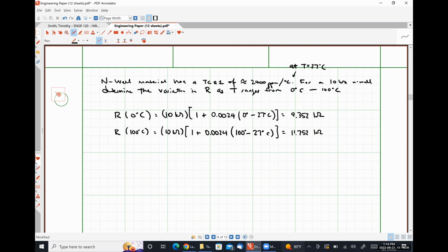So it behaves better under that same temperature range. I'm making this number up off the top of my head because I cannot remember it, but I believe that the temperature coefficient of resistance for high-res poly is measured in parts per billion, not parts per million, okay? So it's significantly more stable due to temperature variations. Yet another reason to use it.